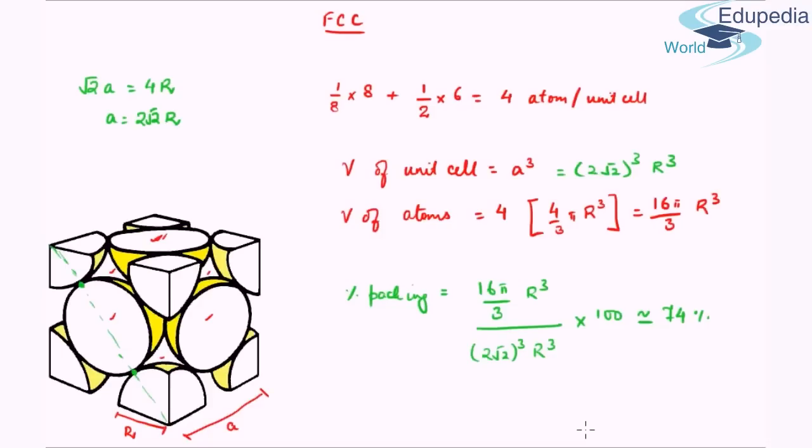So what we can say is body centered cubic is not very dense packed. Face centered cubic is better packed than body centered cubic, but still there are a lot of voids left. Now, as we'll see in future lectures, these void spaces present due to ineffective packing will come in quite handy while alloying. These are the places where atoms will go and reside in case of alloying with a small atom. We put that thought on hold for a later lecture.